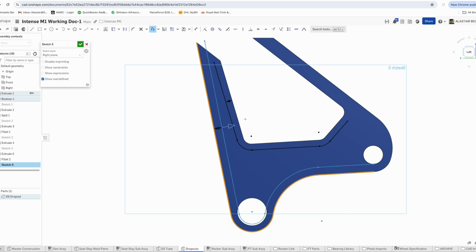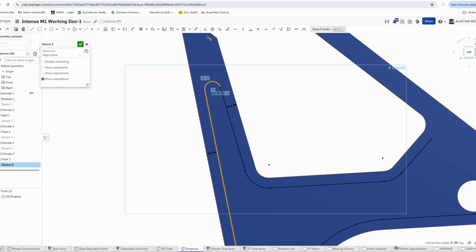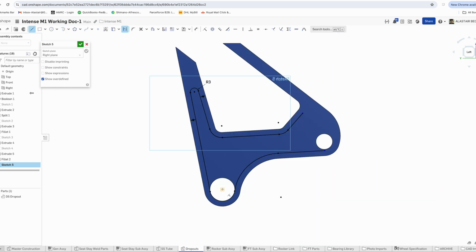But for the purposes of this, I'll skip that and we'll go straight to the pockets on the back of this part. So again, much like we've done with the pocketing in the front triangle and other areas, it's just a bit of an offset from there and then offset to the outside surface, leaving a couple of mil wall thickness.